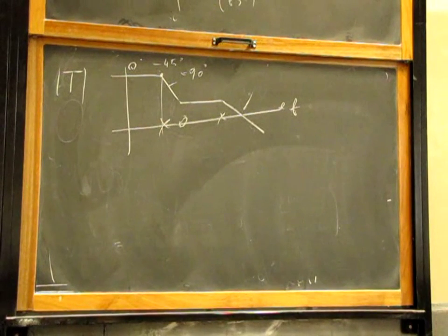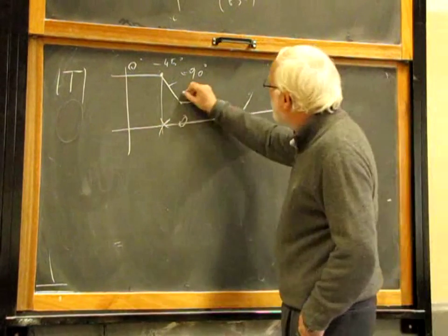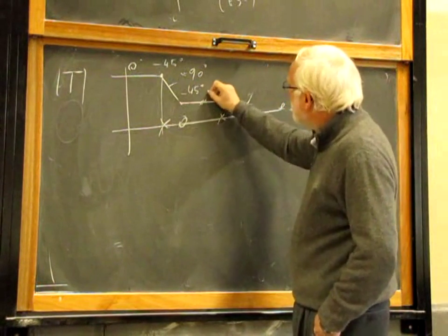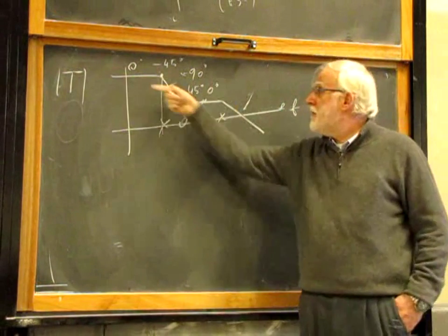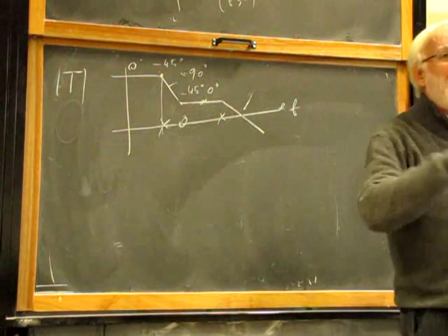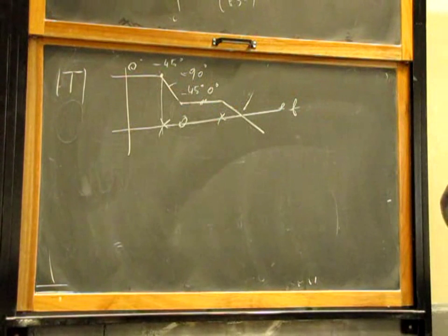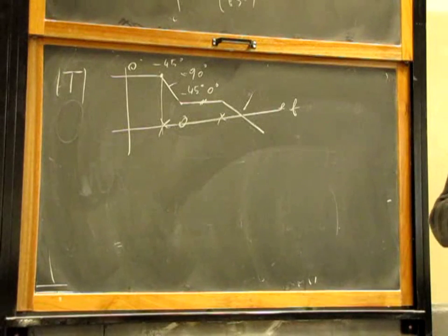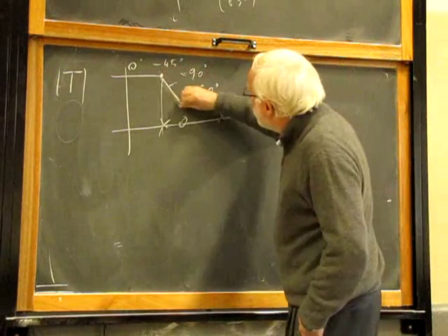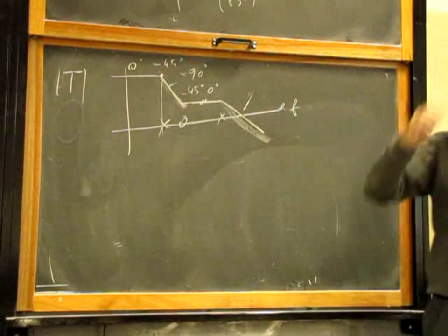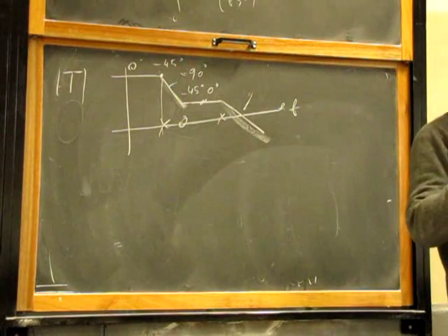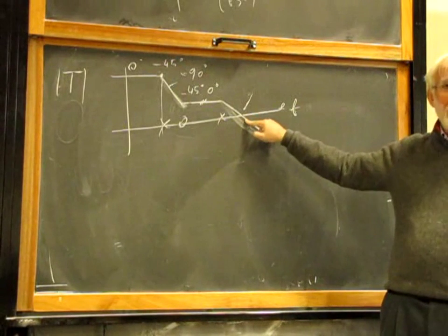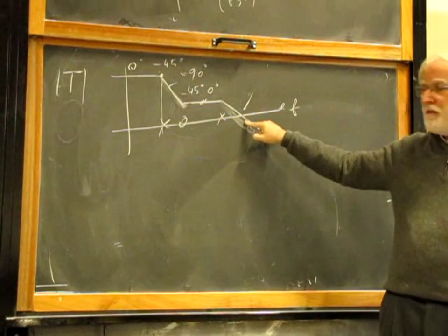The phase by 90 degrees overall. Here the phase will be negative 45 degrees. Here the phase will be 0. Because remember, if the Bode diagram is flat, in the flat region you can only have either 0 or 180 degrees phase, nothing else. And when the slope is positive or negative 20 dB per decade, going down, going up, the phase over here can only be either plus 90 or negative 90 degrees.